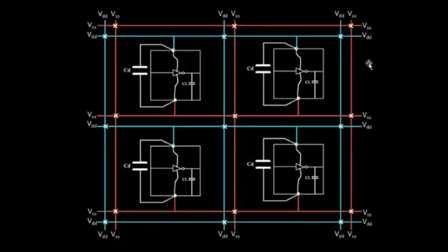We have multiple VDD and VSS lines, and now if this particular block demands current, this is taken care of by the decoupling capacitor. If some logic sitting over here demands a current, it will take the current from the nearest power supply, or it will drop its current to the nearest ground. It does not wait for a power supply sitting far away, but can tap the power from its nearest power supply.